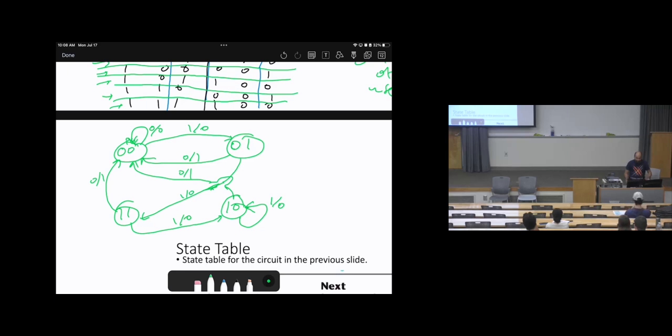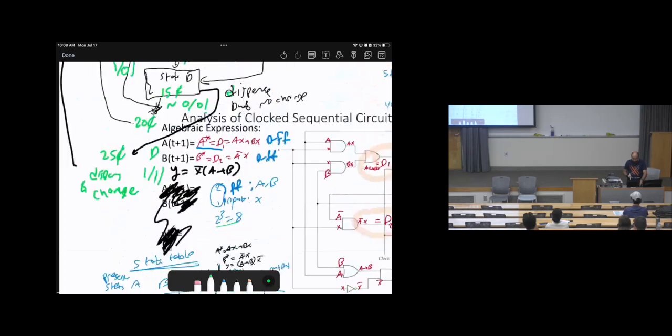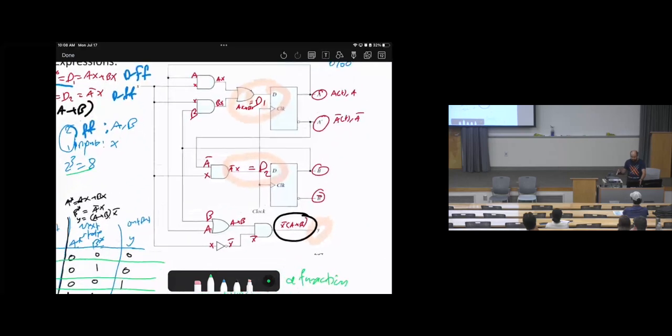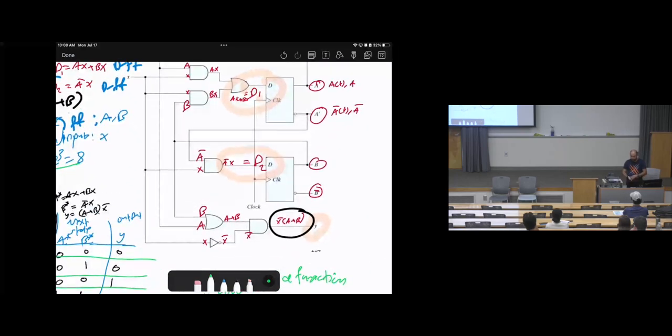So that's like we did a reverse engineering, converting the circuit that we have. First, identify all of the gates: AND, OR, NAND, exclusive OR, etc. Then look at the storage elements: D flip-flop, JK flip-flop, T flip-flop, SR flip-flop, D latch, and so on.